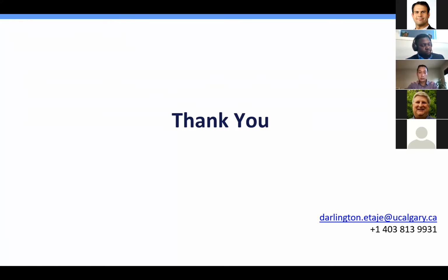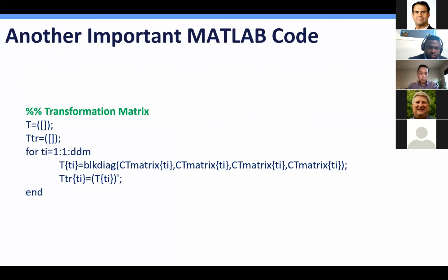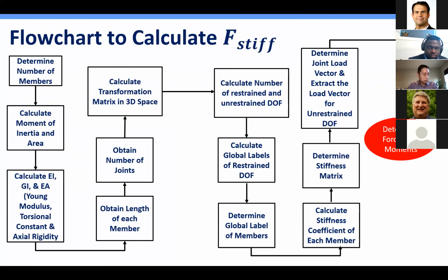I have one question. I know there's lots of them that are going to show up, but in terms of post-buckling behavior, if you go to the stiff string model, do you account for the, I'll call it, change in axial stiffness as I buckle inside of a hole? So I've got a constrained buckling. You know, I'll go into helical buckling. In real life, it is constrained to be some kind of a wavelength. I didn't see where that would actually account for that deformation to spiral, or if you will, inside of the hole. Helical would be a helical path inside the hole.